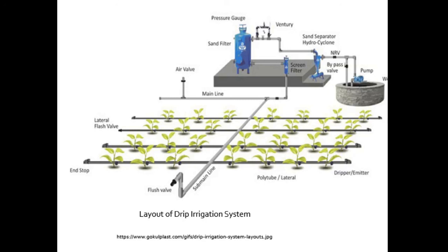The other disadvantages of drip irrigation are that in lighter soils, subsurface drip may be unable to wet the soil surface for germination. It requires careful consideration of the installation depth, and furthermore, waste of water, time and harvest also occurs if not installed properly.